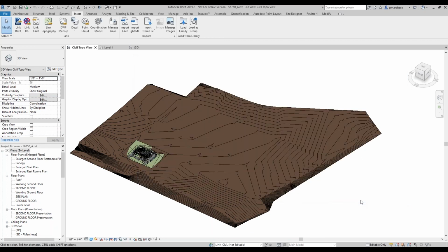I should mention, Peter, that if there are changes to the surface in Civil 3D, you do have to publish it again. It's not just an automatic thing. You have to publish it and push it up to BIM 360, but still, it's just a quick step to do.